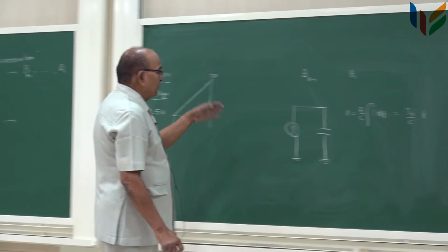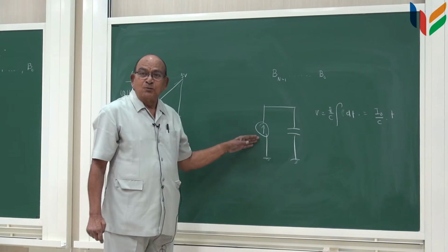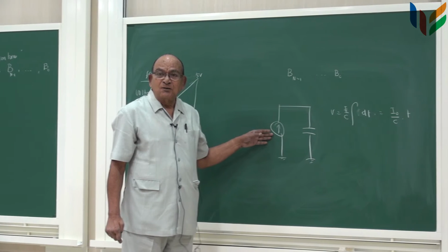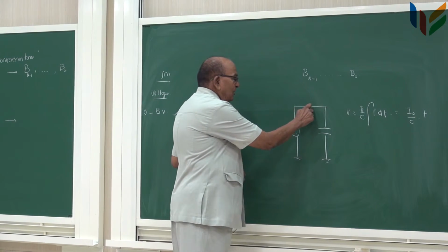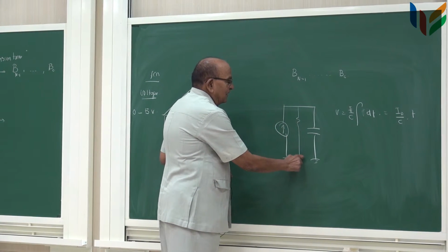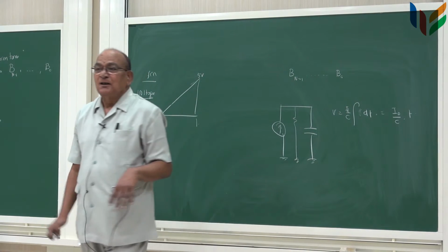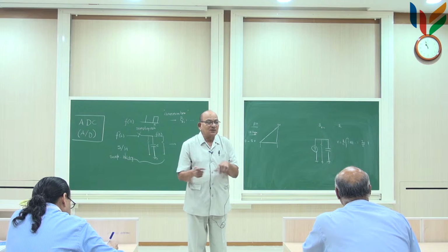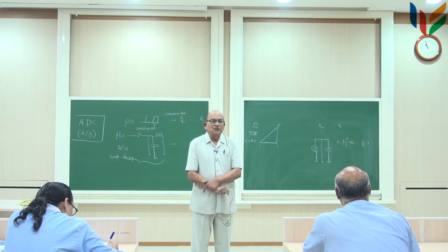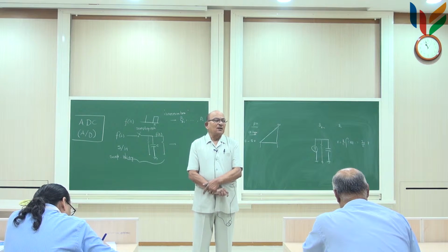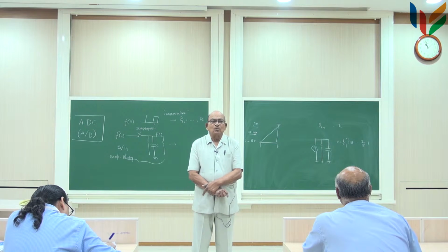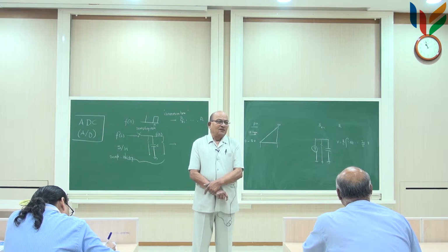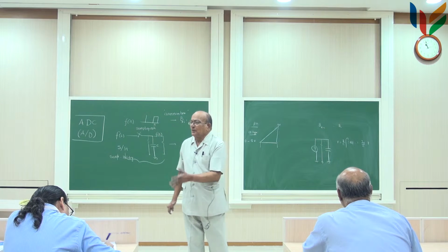Of course, I shifted the problem to this now, and this should really be a constant current source. In addition, the so called internal impedance of this should ideally be infinity. Otherwise, the same RC time constant problem will come again. So, it should be very large. So, you must make a current source which is almost ideal and then use it for charging a capacitor.